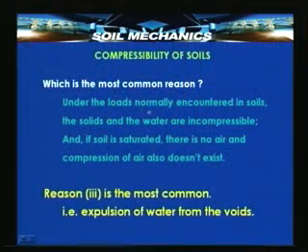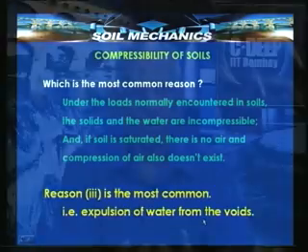So, what is the most common cause for the consolidation phenomenon of the various possible causes that we saw? The most common cause is, under the loads normally encountered in soils, the solids and the water are incompressible, and if the soil is saturated, there is no air and no compression of air is also possible, and therefore, reason 3, that is the expulsion of water from the voids, is the most common reason for the consolidation to occur.